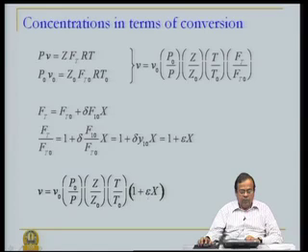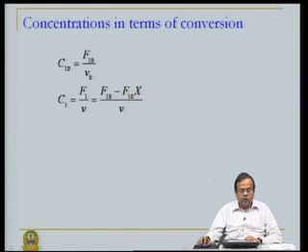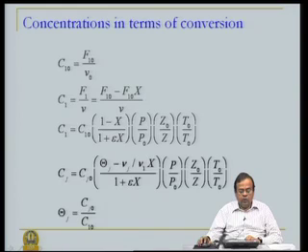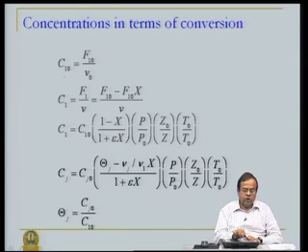I will quickly wrap up today's lecture by saying that this information in turn is related to the concentration changes. So, let us define the concentration at the inlet as molar flow rate divided by volumetric flow rate. So, moles per minute divided by liters per minute, giving rise to moles per liter.